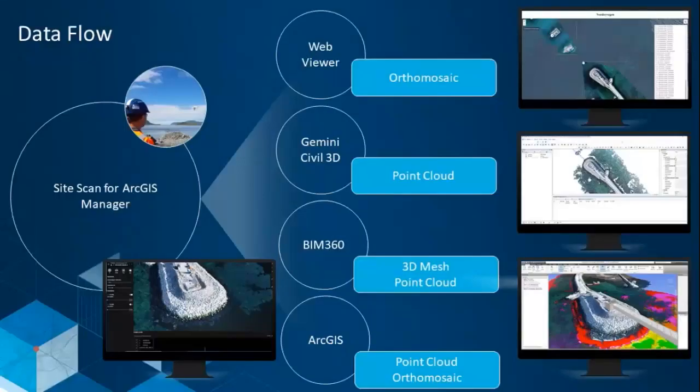So this is basically the workflow we use here at Skanska Norway. We started a year ago with basically no idea how to build this system, but now after around 100-something flights, we think we have a quite efficient data flow system. We basically fly the same areas every time, so the pre-flight planning in the office is now at a minimum. Our ground control points are mostly set and maintained, so there is not much pre-flight field work either. So we just travel to the area for mapping, do the safety measures, and start flying.